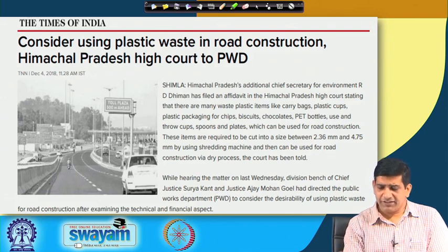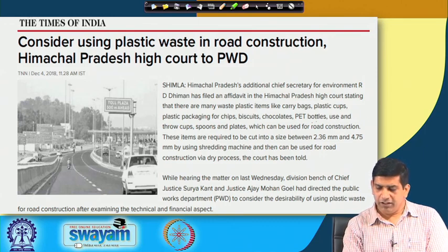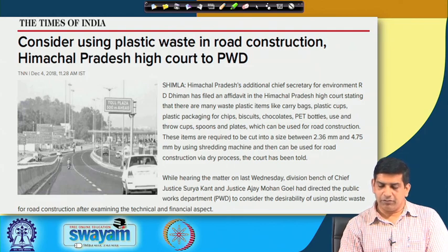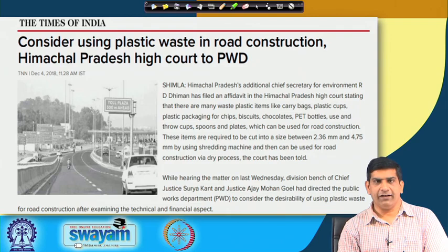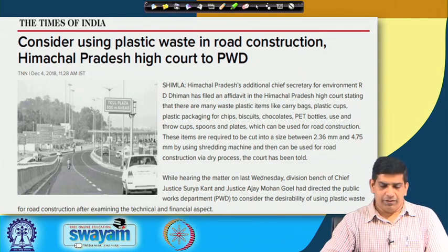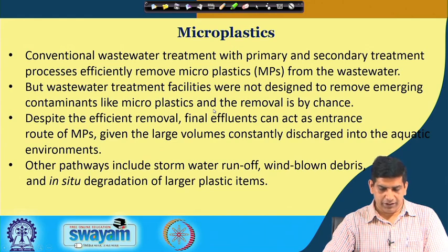So here the Himachal Pradesh Additional Chief Secretary has filed an affidavit in the Himachal High Court. There are many waste plastic items like carry bags, plastic cups, plastic packaging, chips, biscuits, chocolates, and so on, which can be used for road construction and are required to be cut in size to 2.36 mm to 4.75 mm by using a shredding machine. So again, you are using energy there, and then it can be used for road construction via the dry process. So there again, the High Court of Himachal Pradesh says that you should decide on using waste plastic for road construction after examining the technical and financial aspects. So some study needs to be done to make sure that we are doing it correctly.